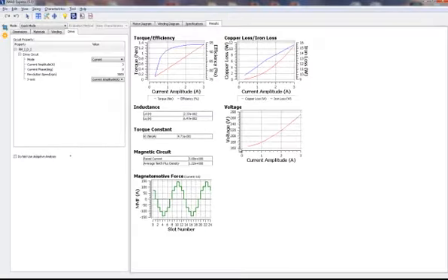So as I mentioned in our presentation, the only drawback is it's very basic. It's a simple constant parameter DQ inductance, and will have some information on the operating range, but not a whole lot of information on the operating range. If I want to go in and create a higher fidelity RT model block for looking at the efficiency map, I'd have to move into JMAG Designer and use our RT creation tool.